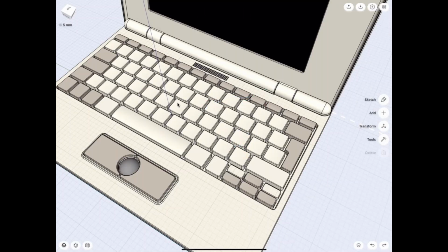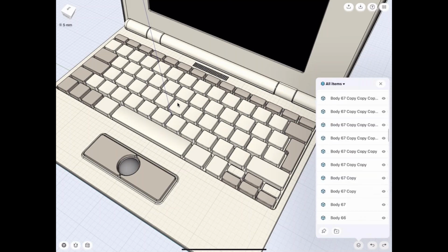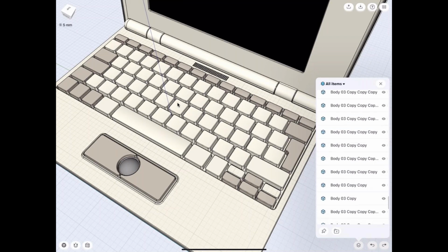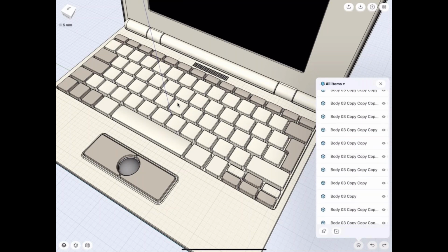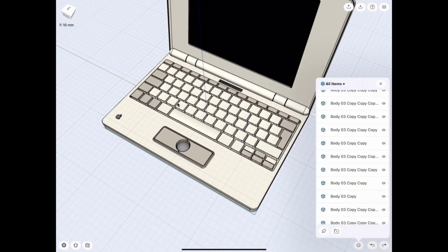But the tip is actually to go through and label all of these layers, because when you import to KeyShot later on, it's really going to help you in understanding what's going on. So to do that, for example, I'm just going to come out of this and name it here.